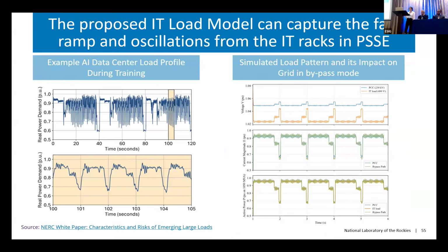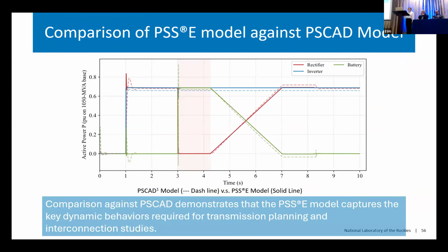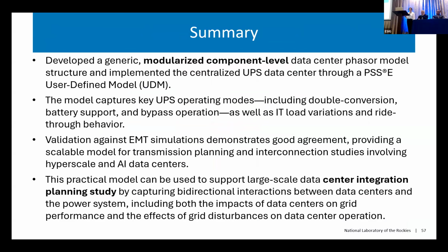The last one, I just want to show you that the right figure is showing, in the NERC report, the oscillations, ramp up, ramp down characteristic, and the left figure is showing our simulation. The last question you were probably wondering is how accurate this Phasor model is. So here we put the PSPD model from PNNL, and it's the dashed line. And also we have the solid line, which is the Phasor model's performance. You can see the very good agreement here.